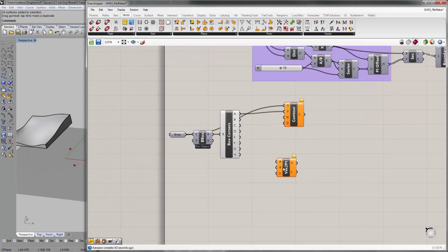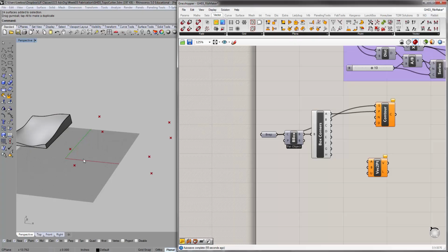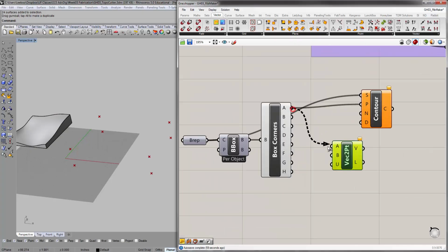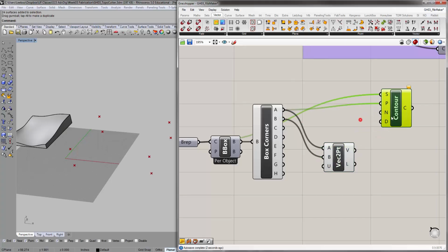So a start point or a base point and a tip point. That's the vector direction. Do you want to unitize output? We don't. So for this, you want to put in A and B basically. So A here, B here, and this vector is what you feed into this N direction.